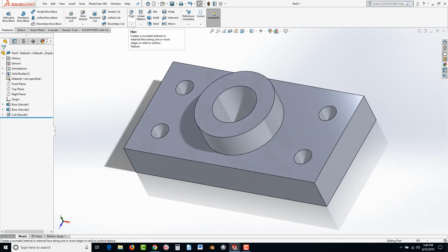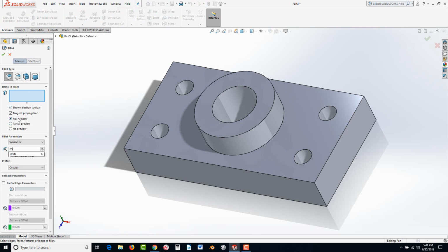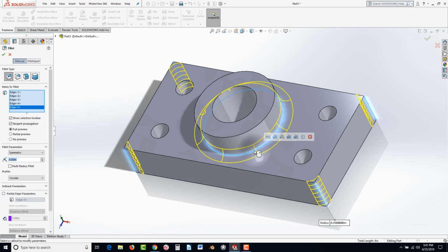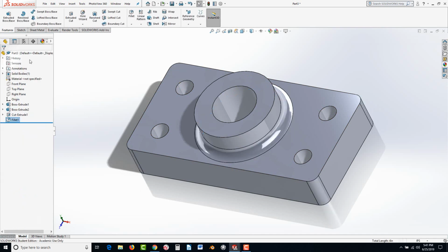There is an order of operations with the fillets and chamfers. Fillets, you generally want to start with the largest fillets and work your way down to the smallest. In this case, they're all the same, 0.25, but there is a 0.1 chamfer at 45 degrees that's going to go on, and we'll put that on last. So go to Fillet first, 0.25, select the 4 corners, use your X-ray vision for that one, and then this edge right here, and hit the green check.